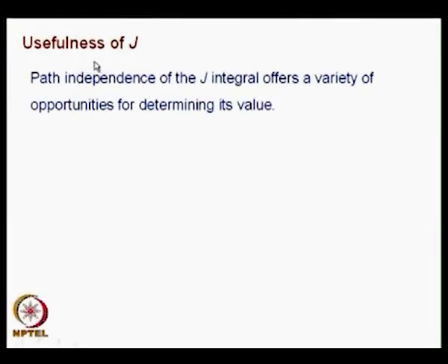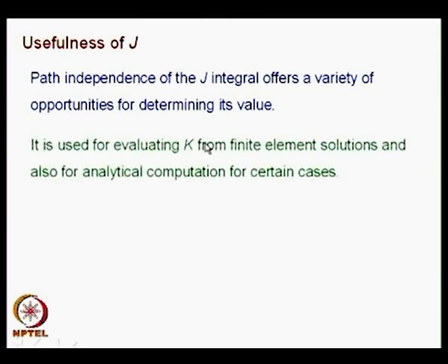What is the usefulness of J? Path independence of the J integral offers a variety of opportunities for determining its value, because I can choose a path which is comfortable for me to evaluate. It is used for evaluating the stress intensity factor K from finite element solutions, and also for analytical computation in certain cases.